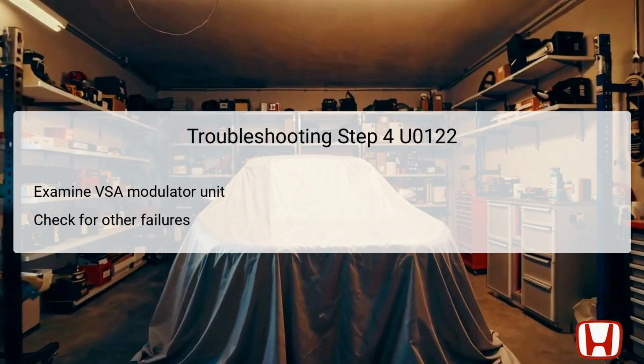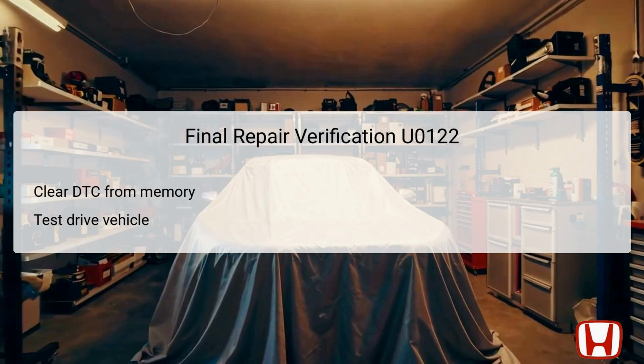Even if visually nothing seems wrong, performing a functional test using a scan tool can be beneficial. This test can reveal internal errors within the unit that are not superficially evident. Moreover, checking for error codes in the VSA may provide additional insights into whether this component is indeed the cause of the issue. After completing the necessary repairs for DTC U0122, the final verification step is crucial to confirm that everything is functioning as expected.